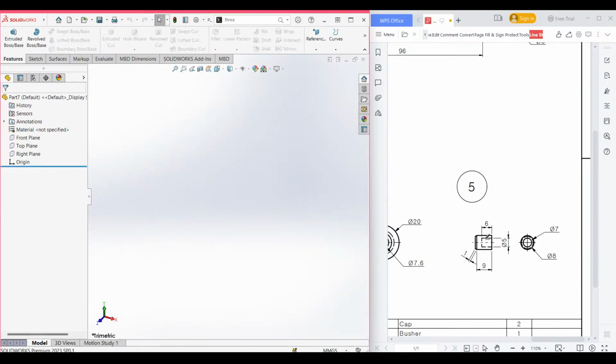This sketch has an outer diameter of 8 unit, and then I proceed to 9 unit, and this 7 unit diameter is showing because of this 1 unit chamfer. If you draw the 1 unit chamfer, this circle will look like a 7 diameter circle. And from the other side we can see we have a circle of 5 diameter of extrude cut of 6 unit. So the 5 diameter circle is to cut 6 units.